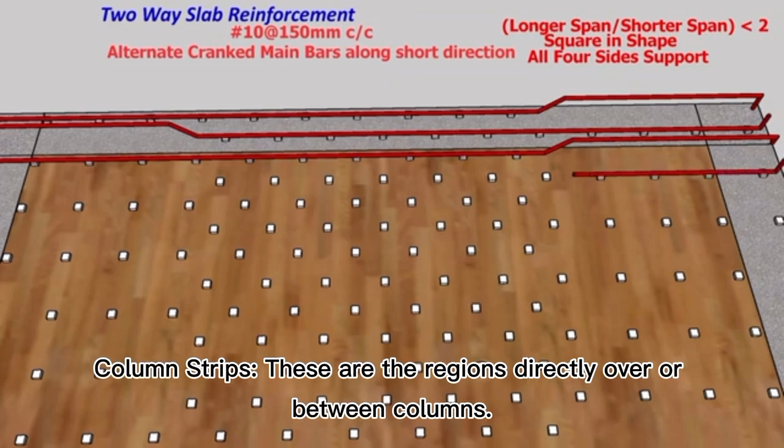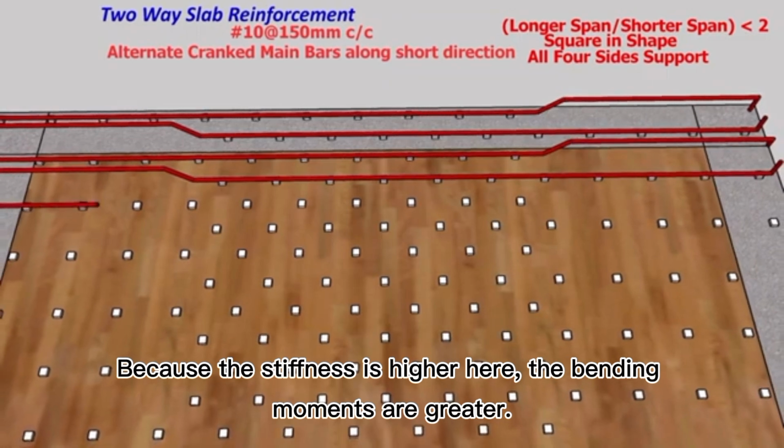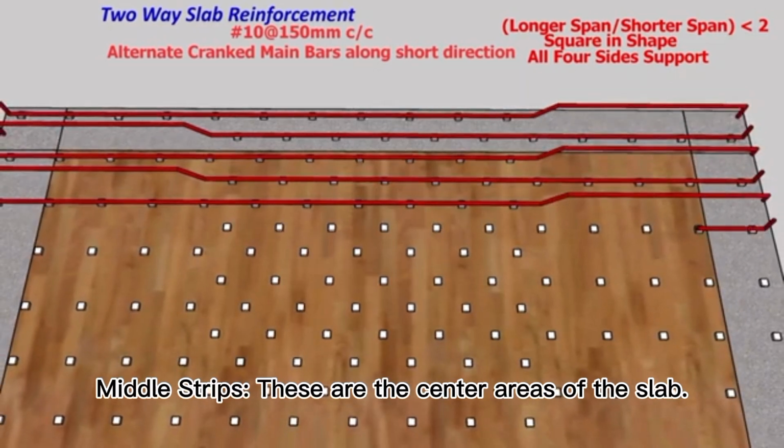Column strips. These are the regions directly over or between columns. Because the stiffness is higher here, the bending moments are greater. We pack more reinforcement into these strips. Middle strips. These are the center areas of the slab.